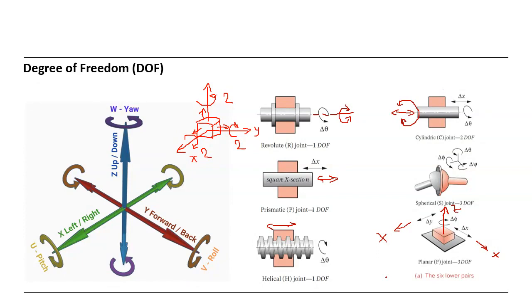And since we have the motion, we have to define degrees of freedom in joints. So which type of motion? Rotary motion, translation, and how can we combine the motion, and we also combine the members, that means the links, and links have to be connected to each other, and then we have to consider which type of joint we need, and which degree of freedom we need, and so on. All those things have to be considered.